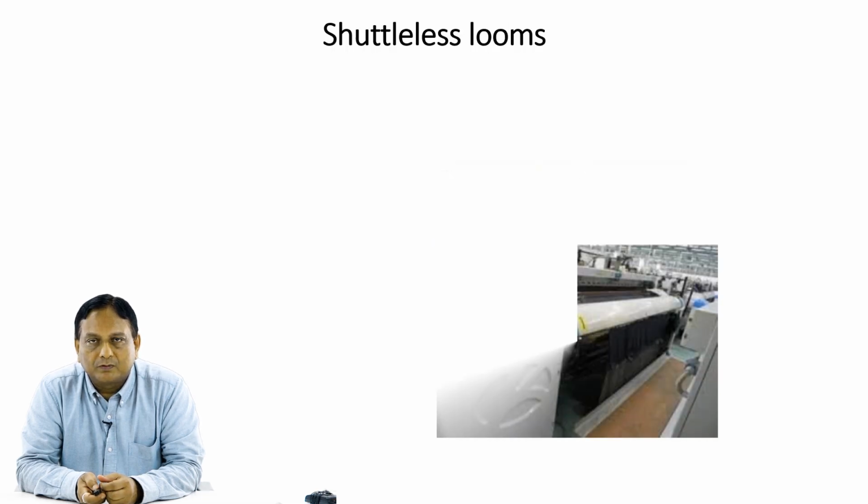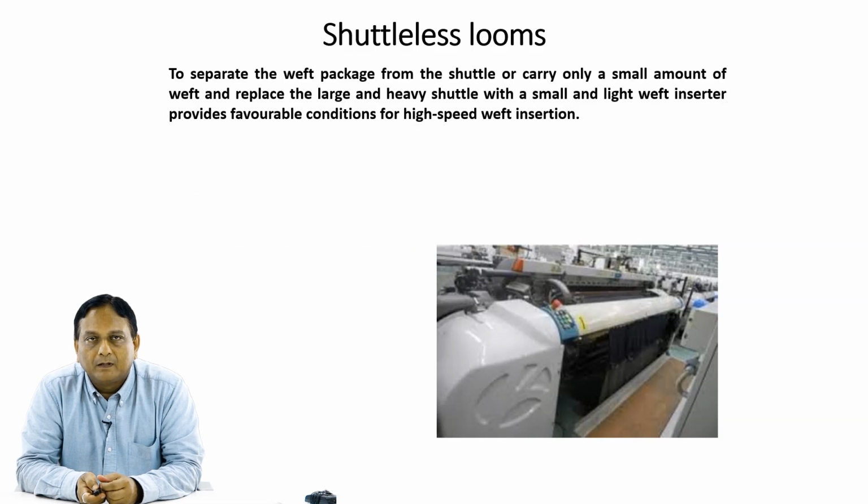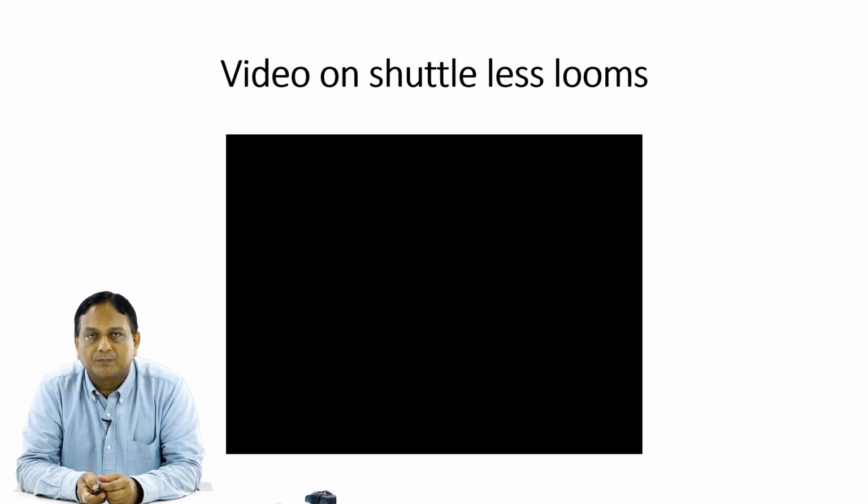Now, shuttle-less looms, as we have seen, so different types of shuttle-less looms we have seen here. It separates the weft package from the shuttle and carries only a small amount of weft, and replaces the large and heavy shuttle with a small and light weft insertion. It has great significance in increasing fabric varieties, adjusting fabric structure, reducing fabric defects, improving fabric quality, reducing noise, improving working conditions, and reducing energy consumption.